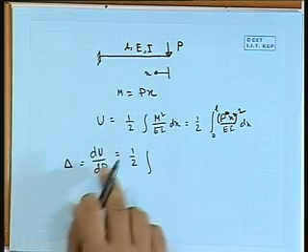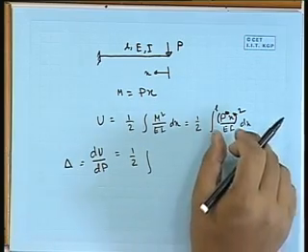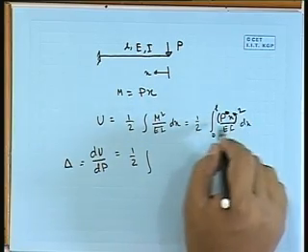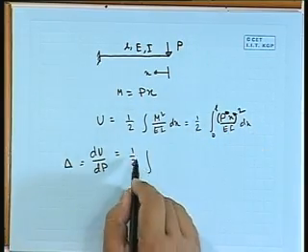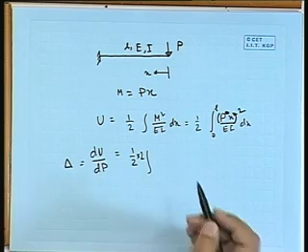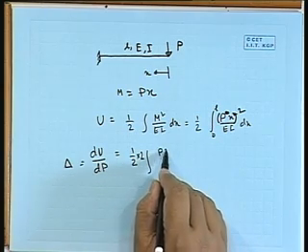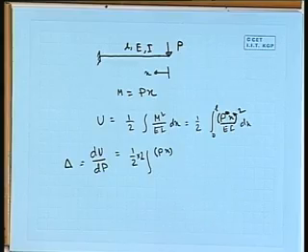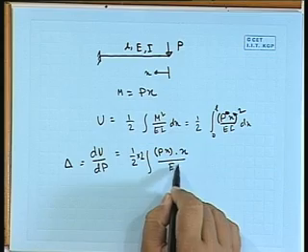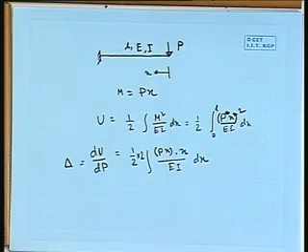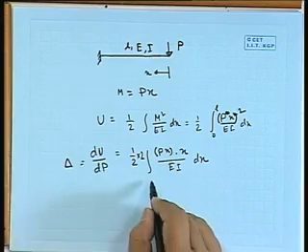Now, delta, du by dp, the square term will give 2 into that px. So, this 2 if you bring outside, it will be px plus the derivative of px, which in terms of p will be x. We are taking the derivative about p, not about x. So, that divided by EI into dx, and definitely it will be 0 to L.